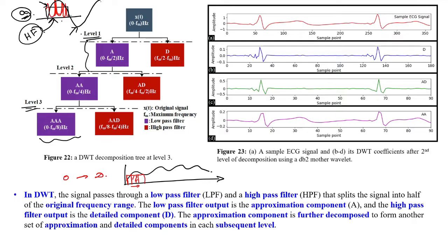Repeat this procedure. So what are we doing here, and what are these filters? These filters are called wavelets, which are present in the time domain. And what we are basically doing here is convolving these scaled wavelets with the signal components occurring at a particular time.